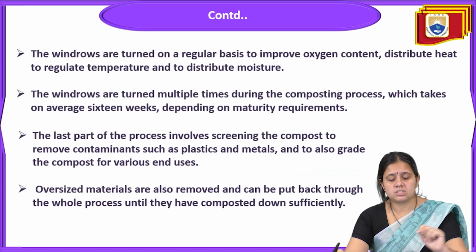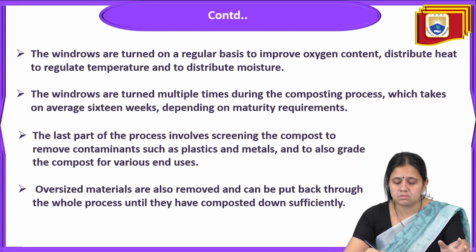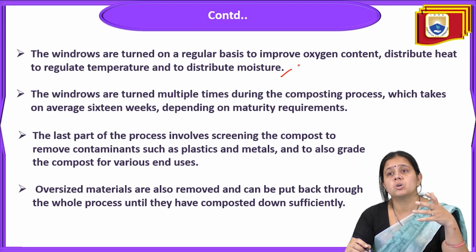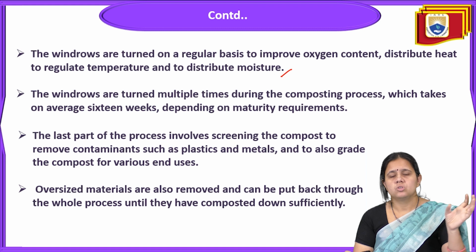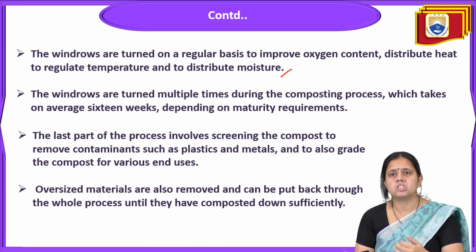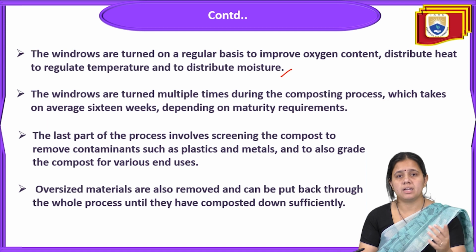Now we'll discuss this windrow in detail. These windrow composting piles are turned on a regular basis only to improve the oxygen content and distribute the heat, so that it will regulate the temperature and the moisture content. If we do not turn this waste on a daily basis, then what happens?